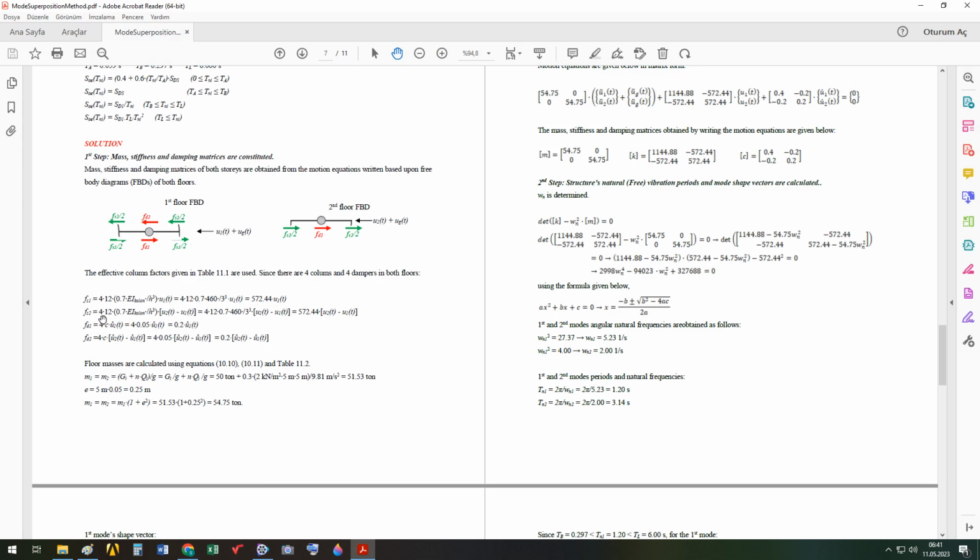Okay, and the damper forces in each story, in each x and y direction, I have 4 dampers effective. So instead of maximum displacement, we use velocities for the damper to calculate damper forces. C is, as given in the question, 0.05. Okay, then I calculate the increased values of lump masses.